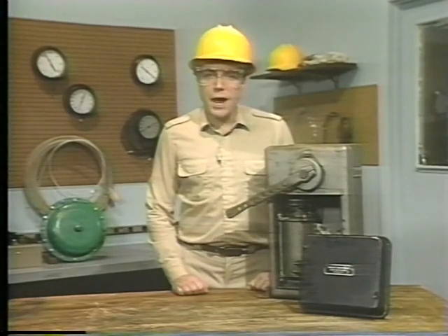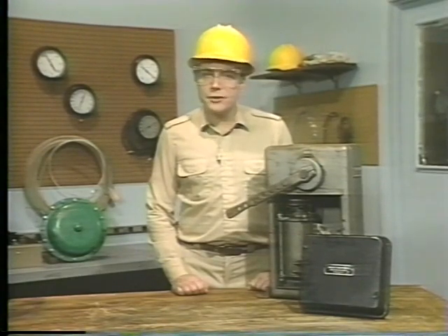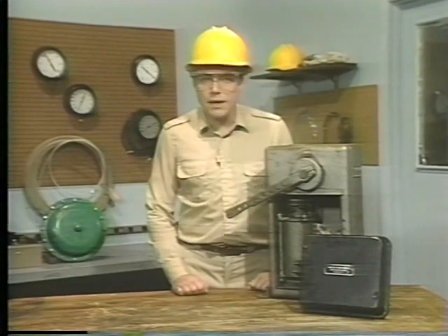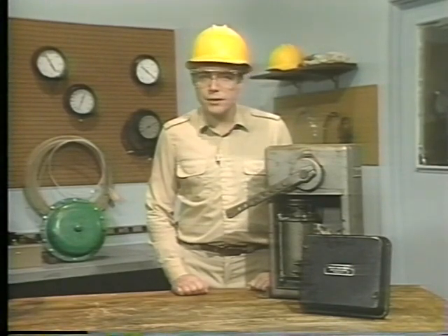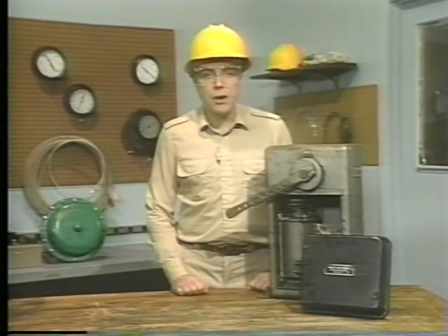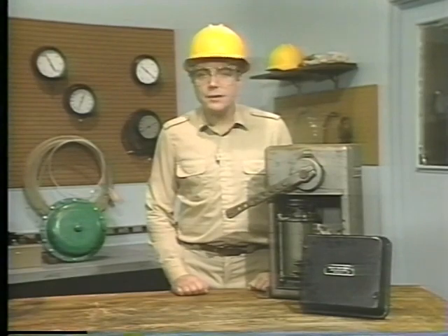Before the positioner and actuator is put back online, an operator at the manual transfer station should apply both 3 psi and 27 psi to the positioner to make sure it operates properly in the manual control mode. Then the system can be put back online and switched to the automatic mode.